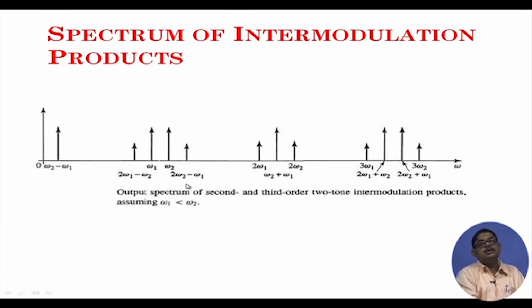So, third order intermodulation is dangerous. I will have to characterize my system so that third order intermodulation should not come, because if it comes it will disturb me. At low values of the input signal, it is not significant, but at some point in high value it starts becoming significant, and I should not take my amplifier into that region or that level where it comes.